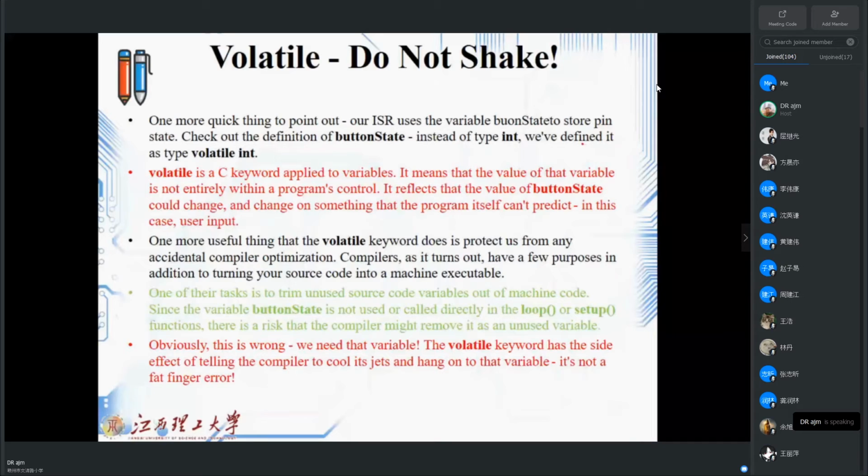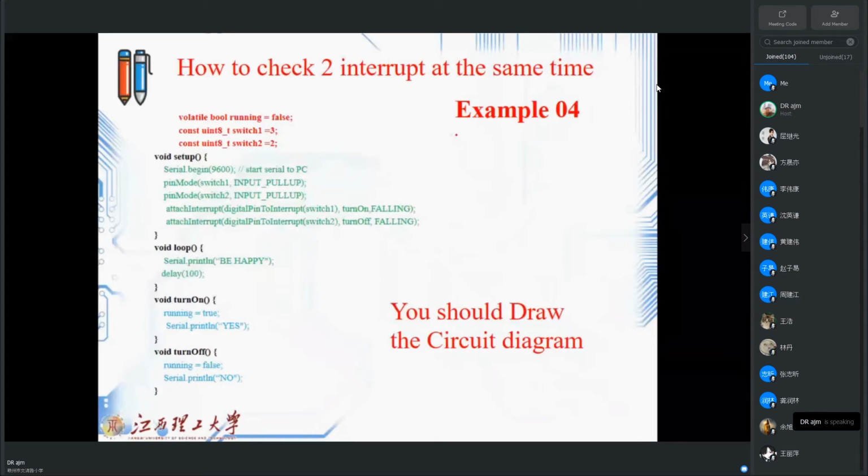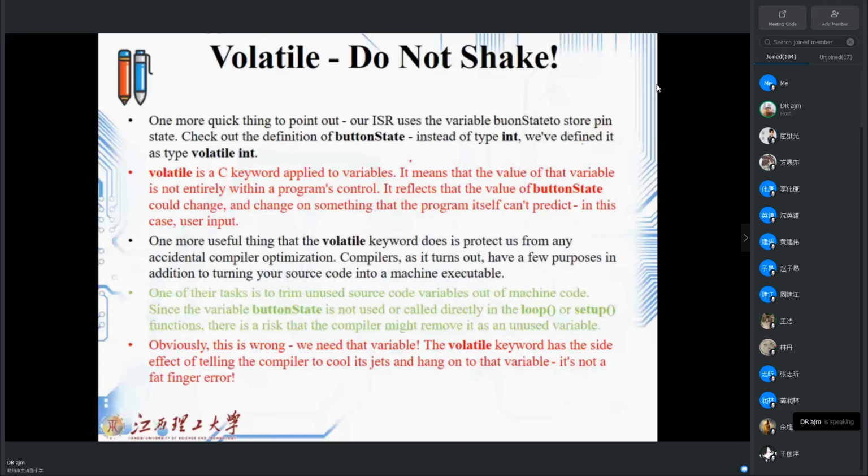I told you that if I want fast programming to sense some external event, Arduino gives me the chance to use two pins on the Uno, which we call pin number 2 and pin number 3, on which external events can be sensed.